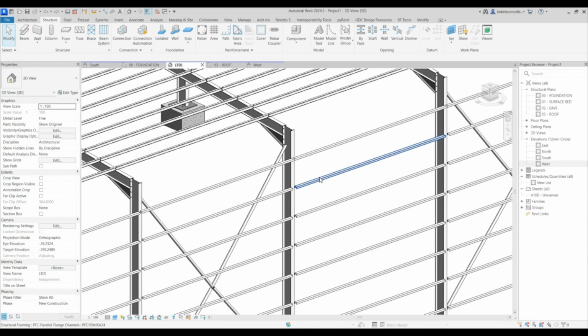Okay, so after the side railings, obviously we can move on towards the purlins. And for the purlins, we're gonna go with connection. Select the two purlins and the rafters, and let's see what we can get. So in this instance, let's see if we can type in vertical tertiary plate. I'm going to select it and press enter. Oh, the side railings are still generating, so we can't apply that connection yet. So we're gonna have to wait for them.